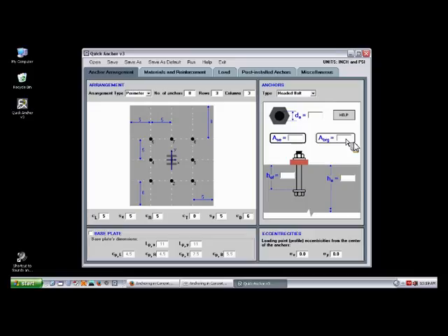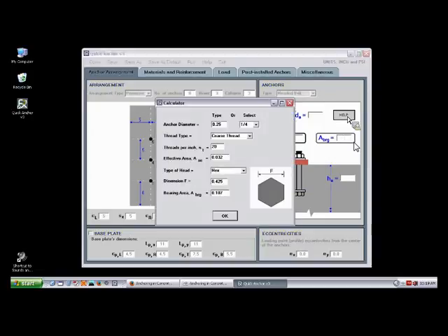And here, if it is a headed anchor, that is, if it is a headed bolt or headed stud, then you enter the head area A sub B or G, which is basically the total area of the head minus the anchor cross section. And in this case, you actually do include the threads. When you deduct the cross section of the anchor from the total area cross section of the head, you do include the thread, so that you know exactly the area of the head that is actually bearing on the concrete. Now, if you don't know your value, all you have is just an anchor diameter that you're using, then you can always click on this help button, and here you can select from 1/4 of an inch up to 4-inch diameter anchor.